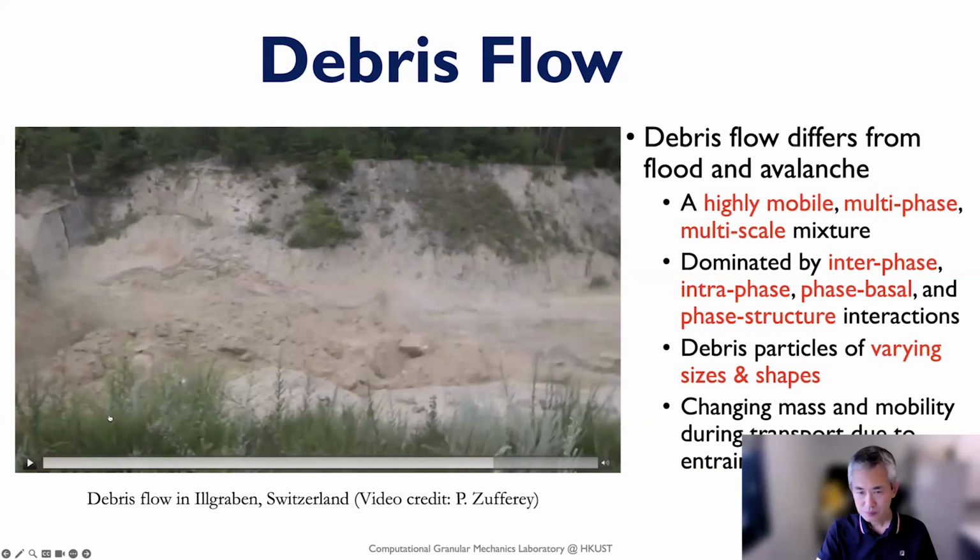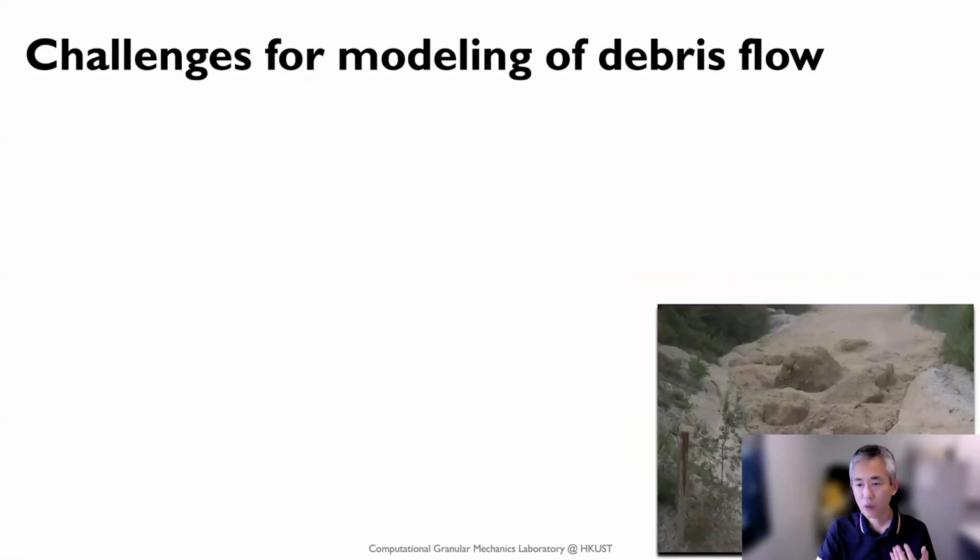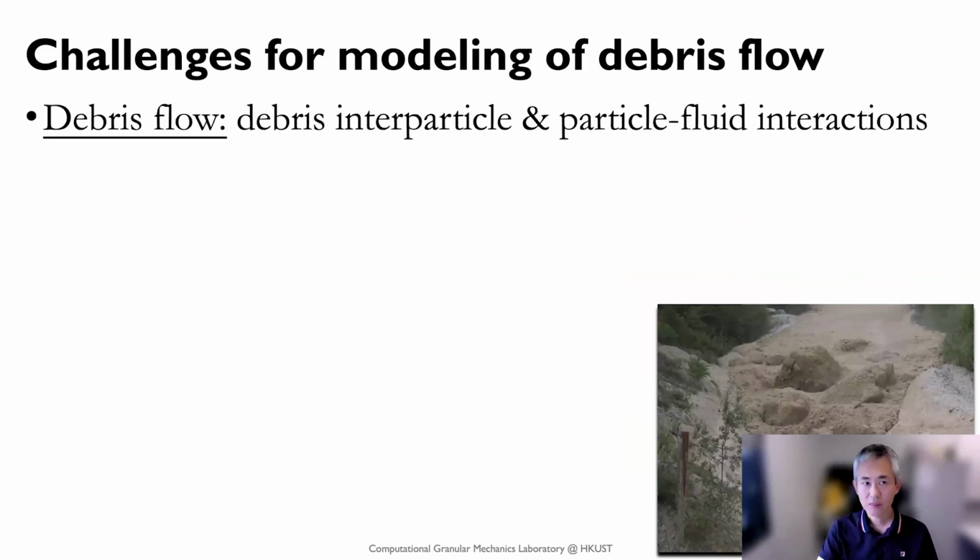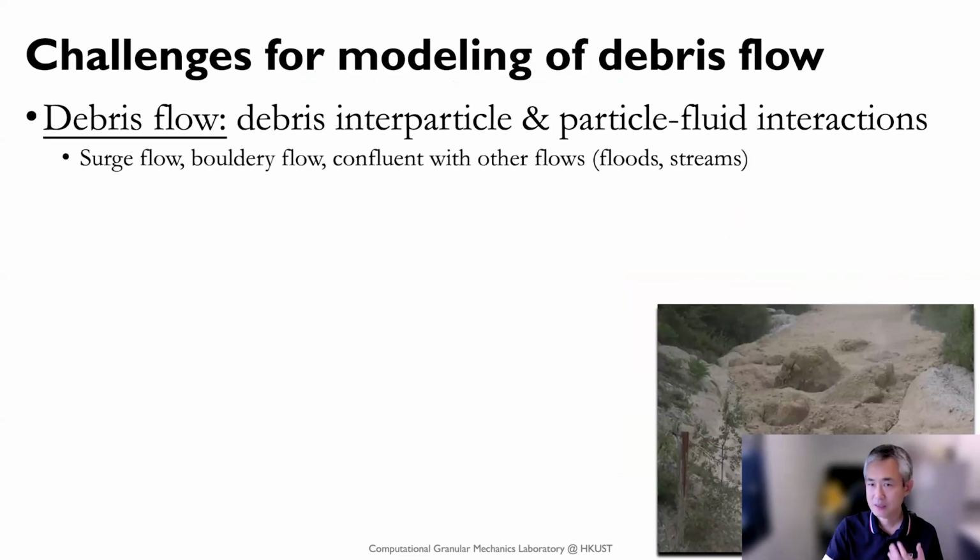Okay. When we look at these distinguishing features of debris flow, indeed these features pose great challenges for numerical modeling. The first major challenge is that we need to consider massive debris particles and particle-fluid interaction, and this interaction is dominant over the different phenomena we observe in debris flow, like surge flow, surge waves, and boundary flow.